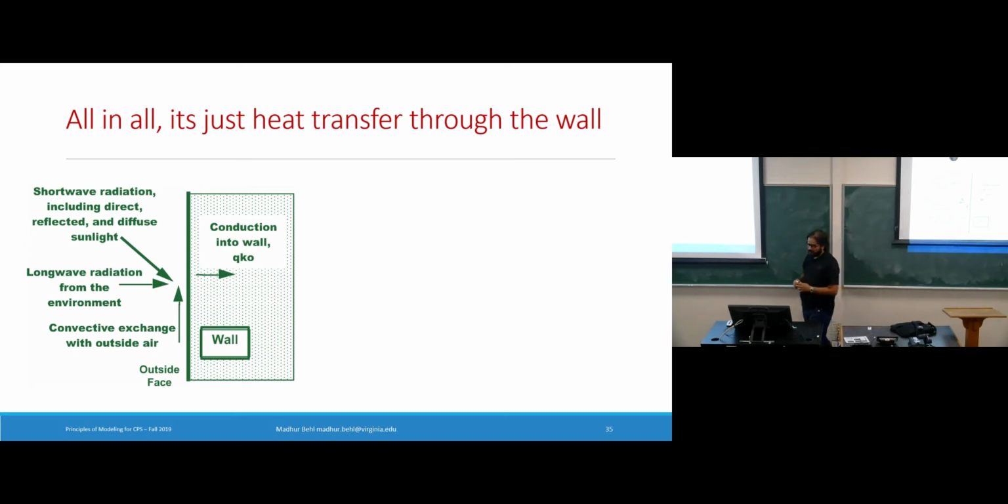So we have direct irradiance on the outside surface of the wall, which is on this left plane. Then there is a convection exchange with the air molecules outside the building, right? It's convection because it's a fluid and a surface, and there is some radiative gain. Because of these causal effects, the temperature of the surface is going to increase over the day.